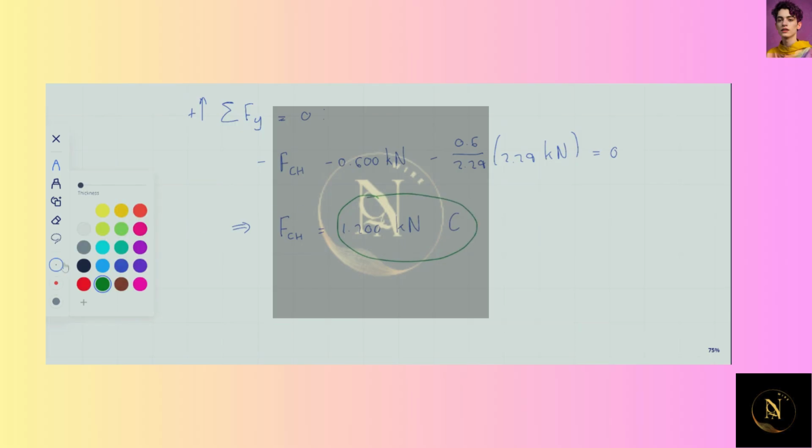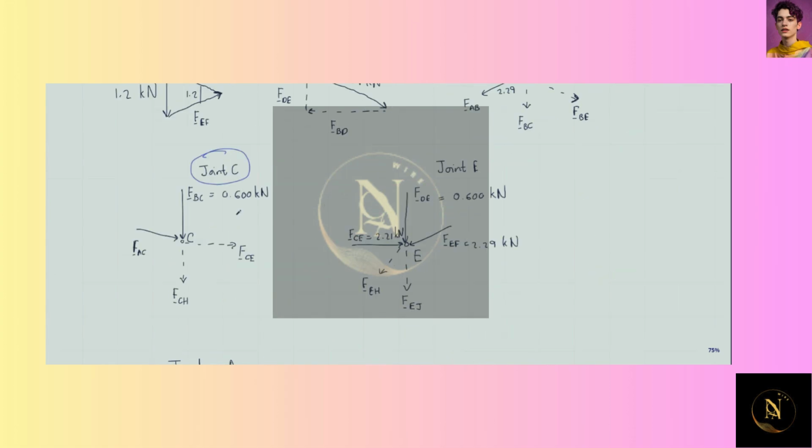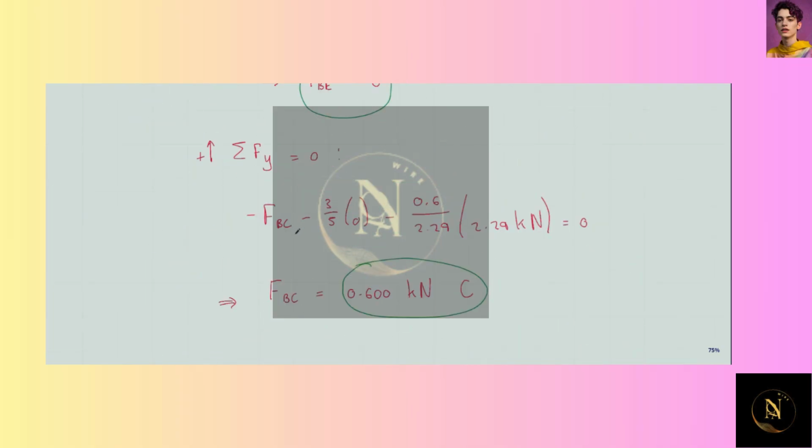Now, lastly, we look at the free body diagram for joint E. So that's the last one we've drawn above. So joint E is as we have in the diagram, and if we calculate our forces from this free body diagram, we can do the same as we did before, taking the right as positive and taking horizontal components.